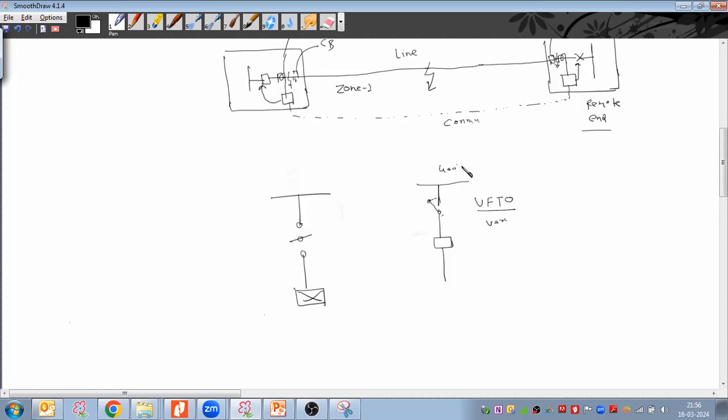kV or 400 kV busbar, right? Here I have zero voltage altogether. Spacing is very less, and then we are closing this switch, right? There would be a higher transient overvoltage during the disconnector closing. And if any fault happens between the disconnector and the breaker, that fault will be in the blind zone unless my breaker is closed and the fault reaches the CT. This CT could not sense those faults.